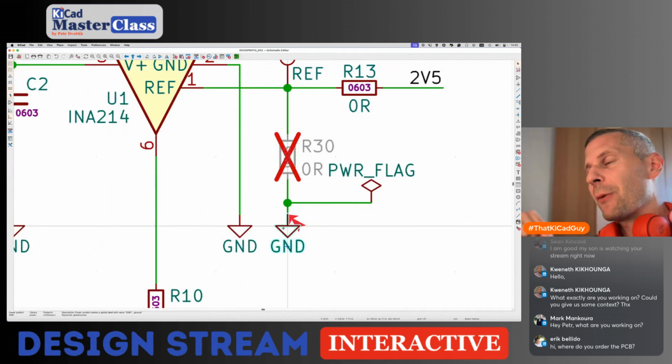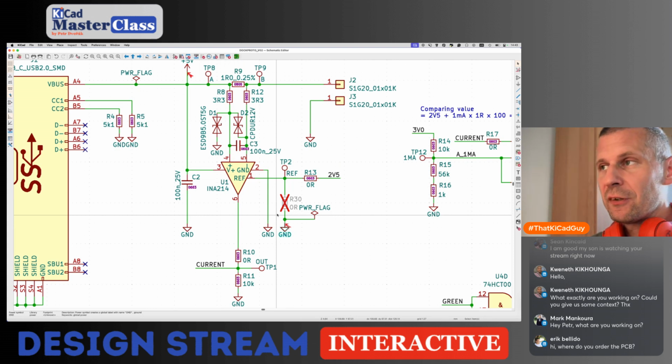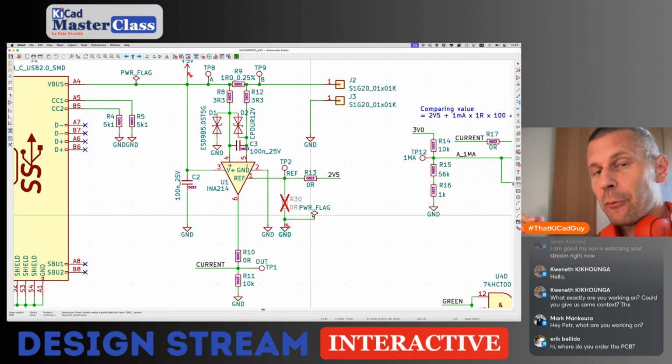So it expects power to flow into the power input. And when there is a resistor, for instance, here, the resistor is passive. It's not a power output. So you always should add the power flag symbol to mark the net as a power providing net.